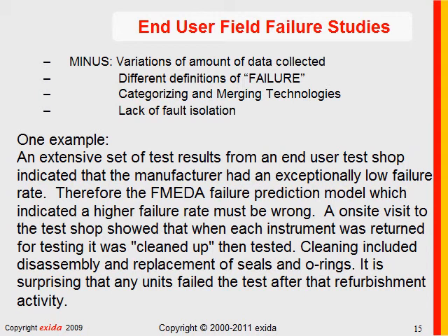The technician, before running each test, cleaned up the valve. This was on a mechanical product. Cleaning included disassembly and replacement of all seals and O-rings. I was totally amazed that any product failed after this refurbishment activity was done. The as-found conditions were not recorded. It's no wonder there were very few failures in this set of proof test data.